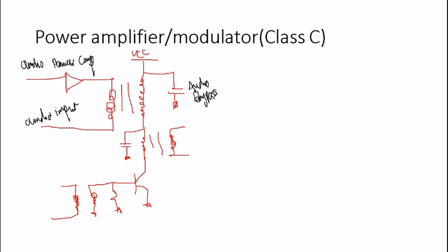The reason why this capacitor is here is that, given that the audio signal is an alternating signal, the capacitor is put here to stop the audio signal from interrupting and allow the signal at this node to be purely a DC value. So it's just a bypass capacitor. Here we have an RF bypass capacitor as well.